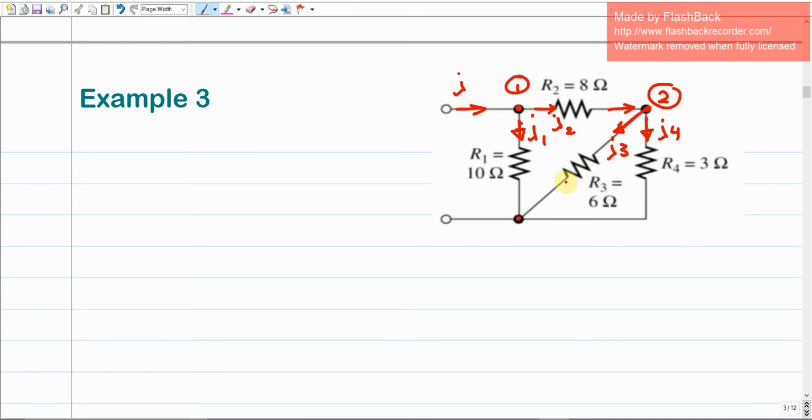And the next to it is directly R3. So if I ask you what is the relation between R4 and R3, you're going to realize that they are parallel resistors. Why are they parallel resistors? Because the current has been divided and split over them. Agree? So what does it mean? It means that it is fine if I combine these two into R equivalent 1, and I'm going to consider that these two resistors are parallel resistors.